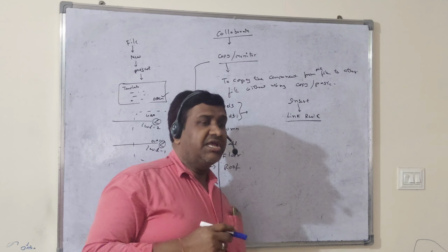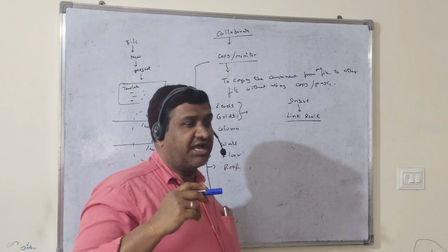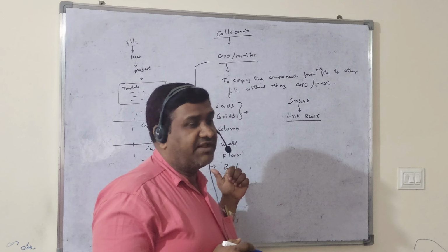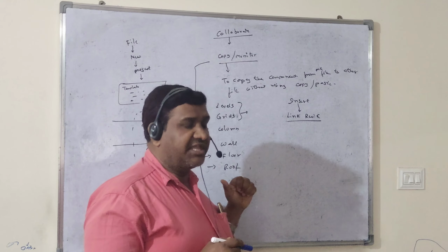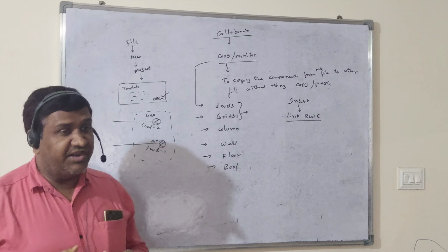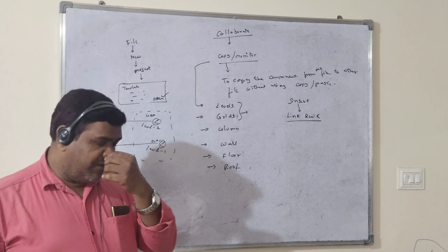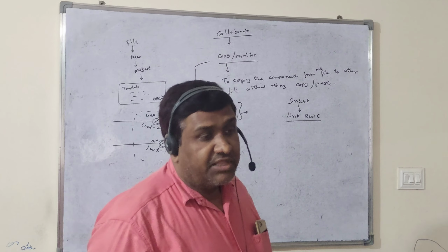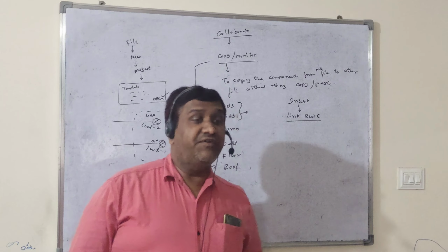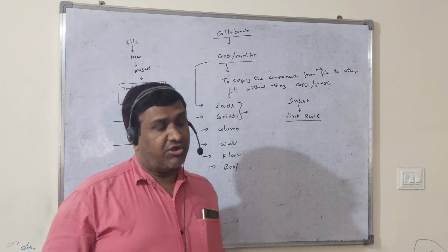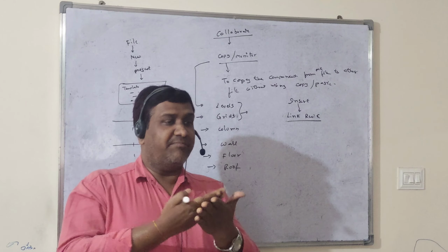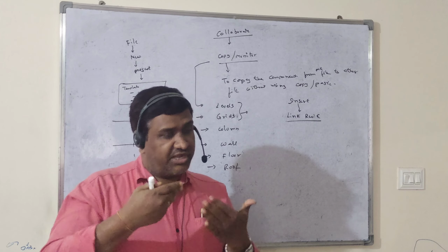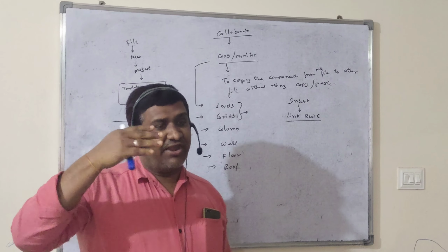Link Revit is nothing but linking a project into your present project file which you have opened. Linking is like an XREF, a reference file. In the technical terms of BIM they call it link, but in AutoCAD, the AutoCAD people call it a reference file, XREF file. In AutoCAD also we can put a number of files as a background, which we call a reference file. In AutoCAD also we can make a number of files as references.